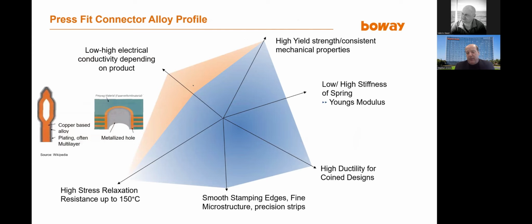If we go to press fit applications as well, something we see as revolutionary in the automotive industry, where actually a pin, it could be just a normal pin, or it could be something with a spring, an eye of the needle, or even with something coining, is connecting directly into a metallized hole and with very high spring forces. And here again, the key points are relaxation, the mechanical strength you have, how stiff you can make the spring, or how soft you want it in order to have the right insertion and withdrawal forces.